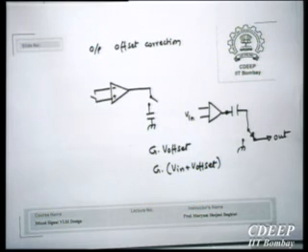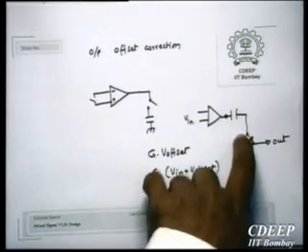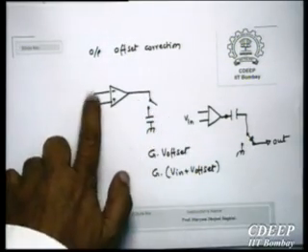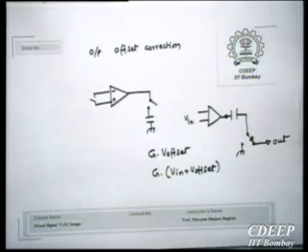By the way, this is the series capacitor with a switch and a shorting switch at the input. That is what you saw in the diagram. Okay, and that charge redistribution A to D converter is ideal for that configuration because you don't have to pay anything. Those things are anyway there. Okay, so you don't lose any time in using this conversion, but that we will come to. So we are coming to that. So then, what is the comparison between the input offset correction and the output offset correction?